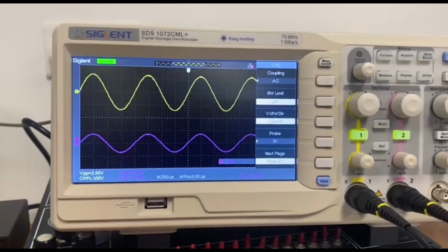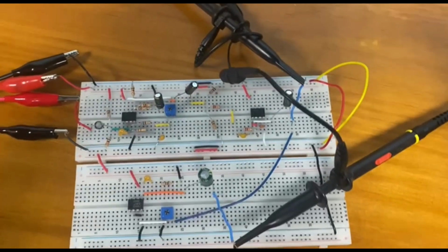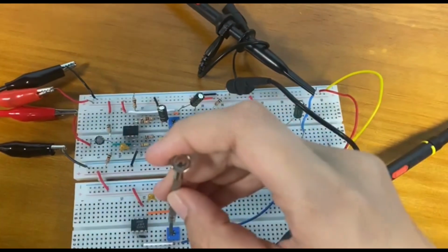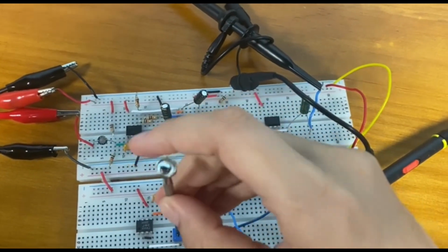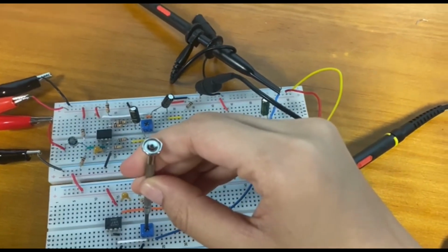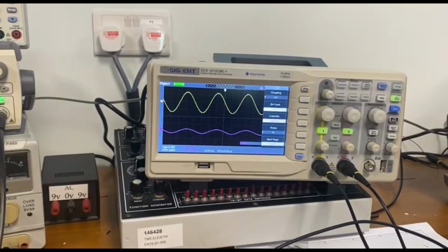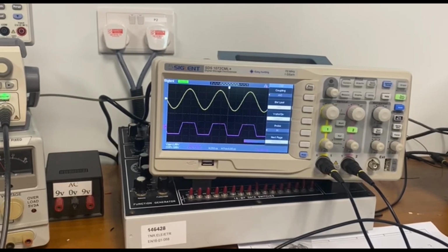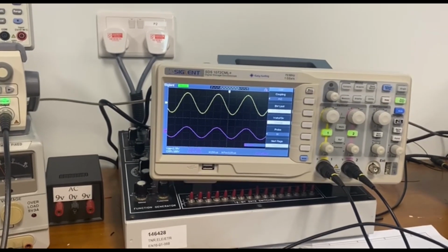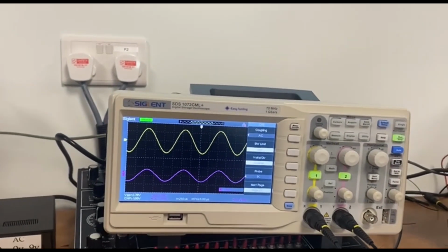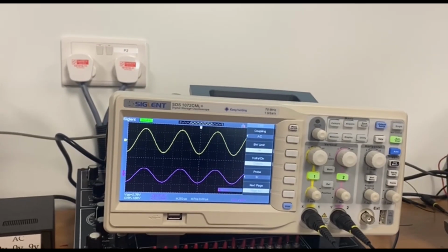Channel 1 is connected to IC2 pin 1 and the negative side of capacitor C13 is connected to channel 2. Adjusting trimmer P2 controls the output at TP5. Turning the trimmer can remove unwanted components. Adjust trimmer P1 to troubleshoot any sine wave distortion, ensuring a clear heartbeat signal for the end user.